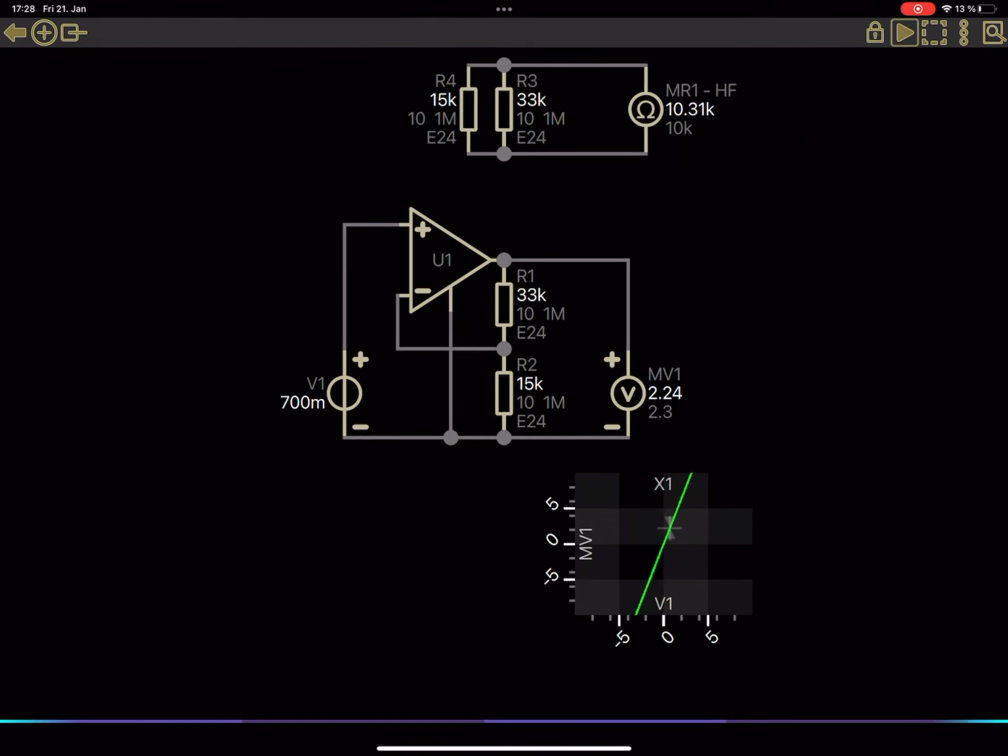Before we finish, one last important thing should be mentioned regarding circuits with multiple target values. Even if you set up a new target value in a way so that it is not in competition with the others, there is a chance that at least some accuracy is sacrificed due to the fact that CircuitShepherd is forced to select auto parts from a discrete set of values. This is the point where it's maybe required to tune the tolerance settings of the target values.